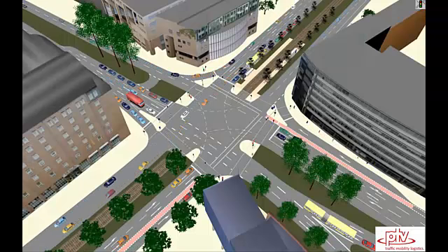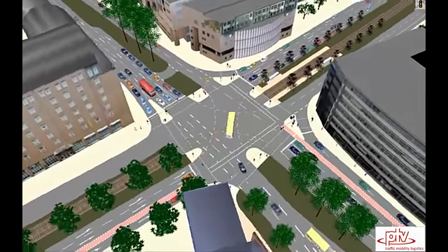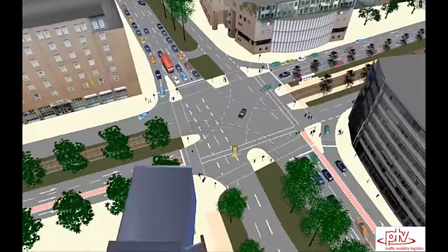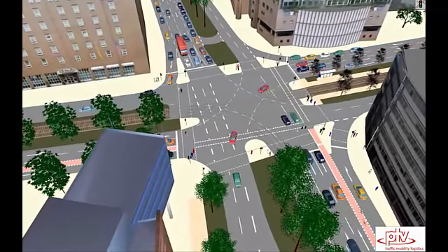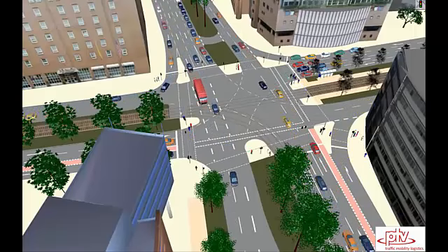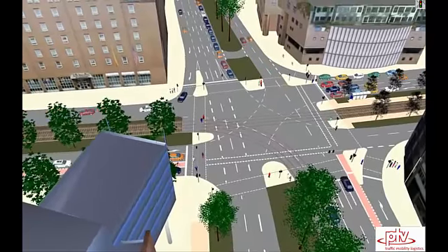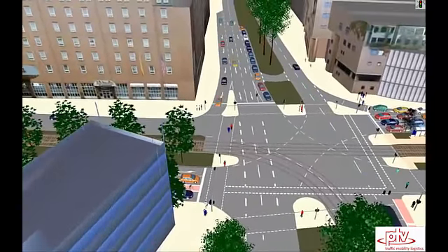The phasing, cabinet, detectors, and actuated controls all work together to produce a safe and efficient service at a signalized intersection. These intersections address highway operations for all users. They allow the shared use of road space by separating conflicting movements in time and allocating delay.